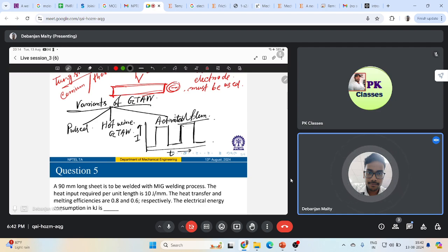And coming to what those things are, basically you will have some improved control. This pulsing will allow for better control of heat input, right? And the weld bead characteristics. So what is the benefit of providing this pulsed operation rather than continuous current supply? Because you are controlling your current as a pulsed current, you are reducing your total heat input.